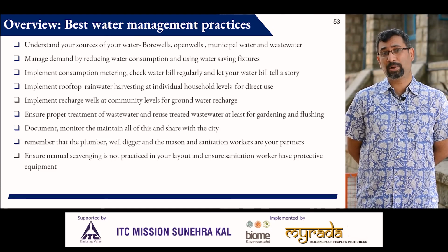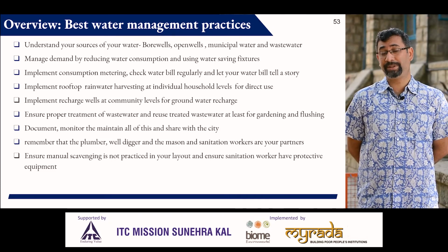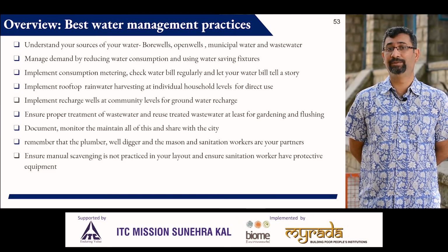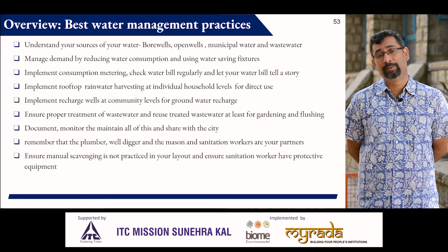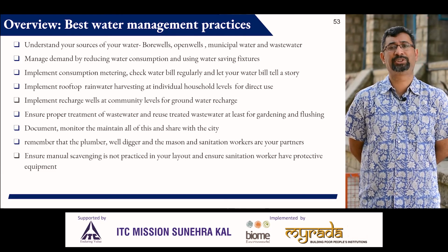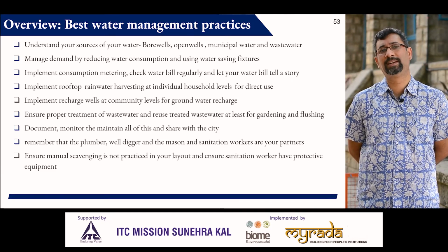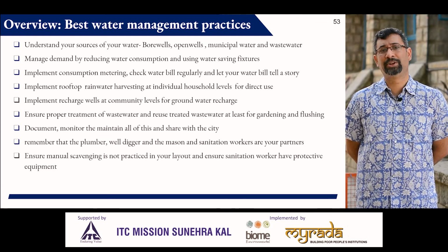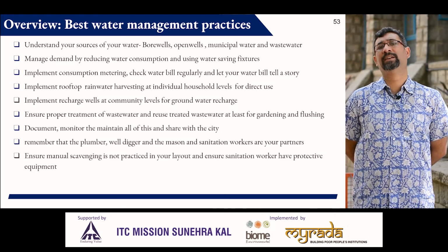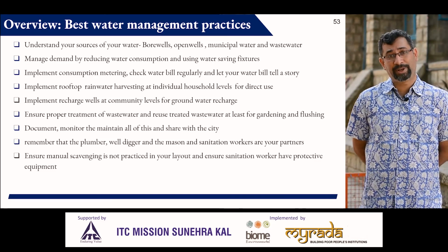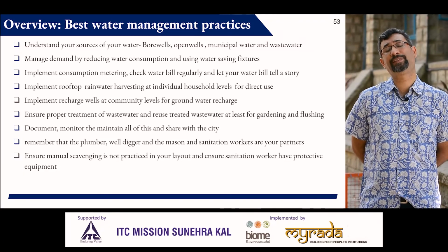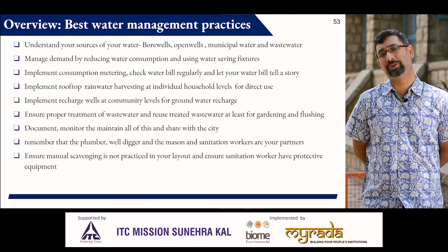When we are recharging water, however, remember that the quality of the water we are recharging should be clean. We should ensure that it's not getting mixed with sewage. We should ensure it's not getting mixed with solid waste. We should put our recharge wells in appropriate places, not very close to electrical cables or sewage lines.